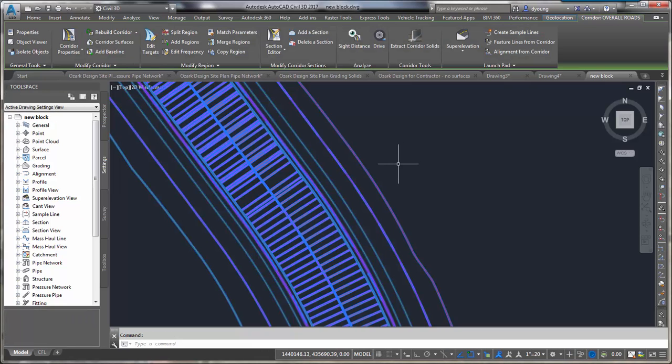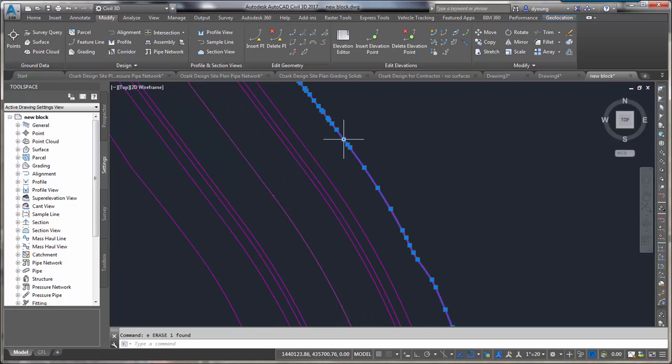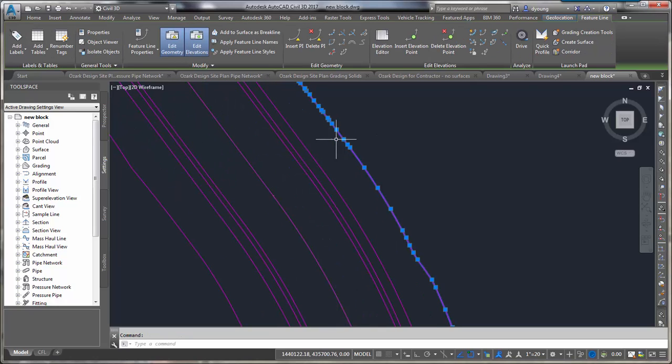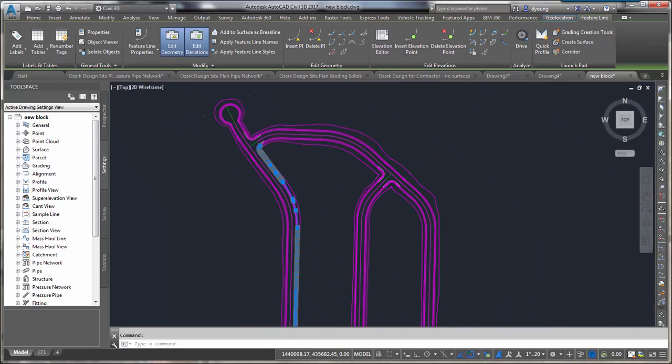And actually, that's the corridor. The corridor is still referenced in there. Let's erase it. And we should see, there we go, just the lines I want. So there's my daylight, there is my sidewalk, back of curb, center line, and it gets it for that entire corridor.